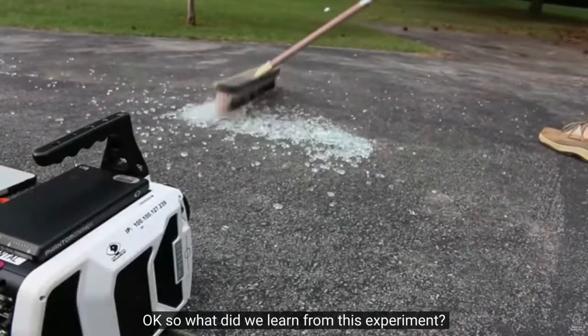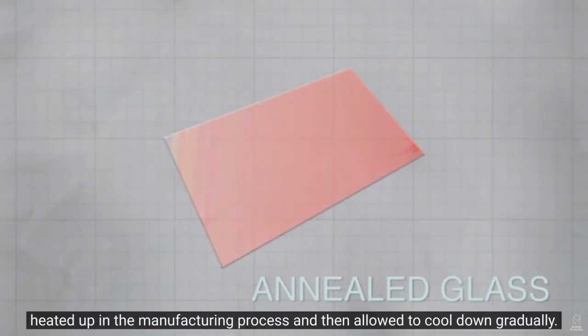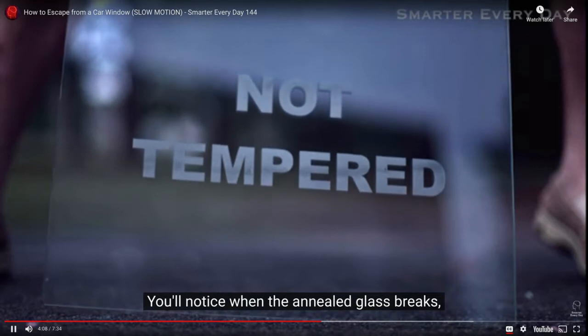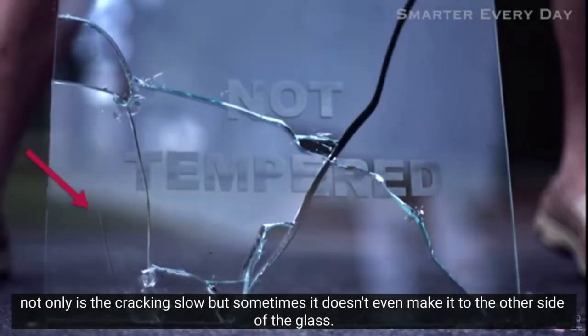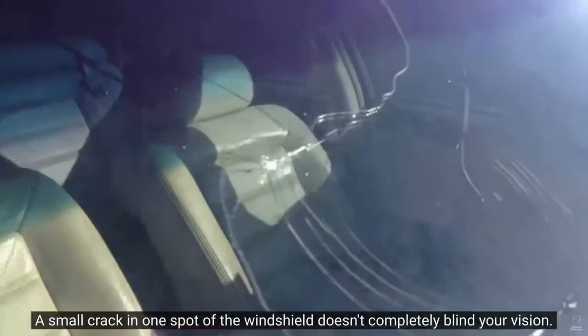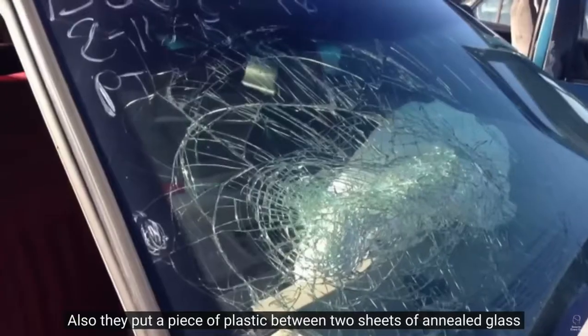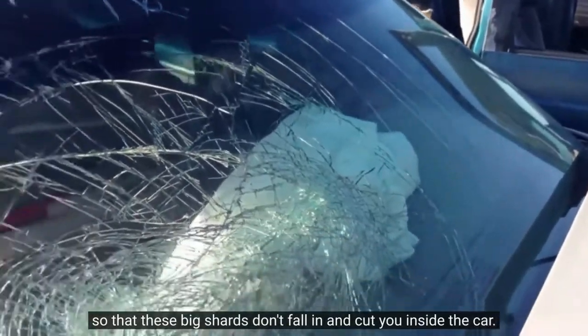Okay, so what did we learn from this experiment? Annealed glass is just normal glass that's been heated up in the manufacturing process and then allowed to cool down gradually. This cooling relieves any internal stresses on the glass. You'll notice when the annealed glass breaks, not only is the cracking slow, but sometimes it doesn't even make it to the other side of the glass, which is good for windshields. A small crack in one spot of the windshield doesn't completely blind your vision. Also, they put a piece of plastic in between 2 sheets of annealed glass so that these big shards don't fall in and cut you inside the car.